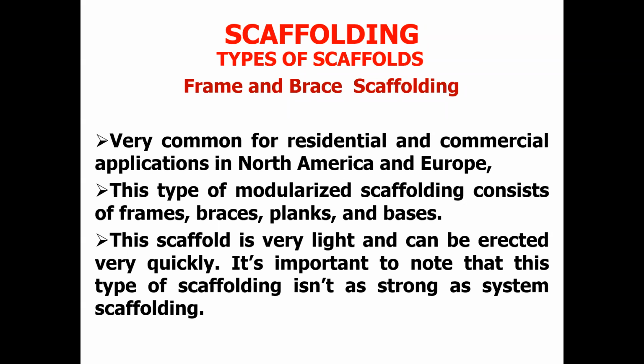Once you place a standard and place another standard at a distance and connect them with ledgers, you also need to have braces. Braces are just there to stiffen the system.